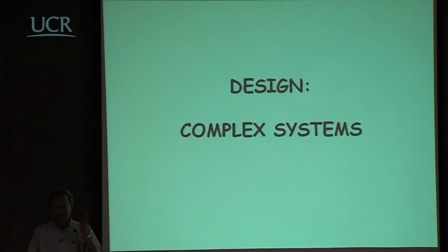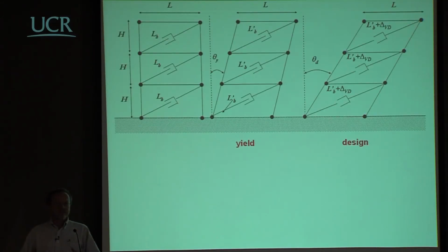Now, about complex systems, not more than 5 minutes. Read the book and you will see, but you could use dampers, for example, in a steel structure where you could consider to have some elongation here, which is the elastic elongation of the bracing, and then to have inside the bracing some kind of damper that will start moving before you reach the yielding in the bracing. So again, you have no damage. Or you could conceive to have, this is a bit expensive, but in principle you could put a whole damper here instead of putting there.